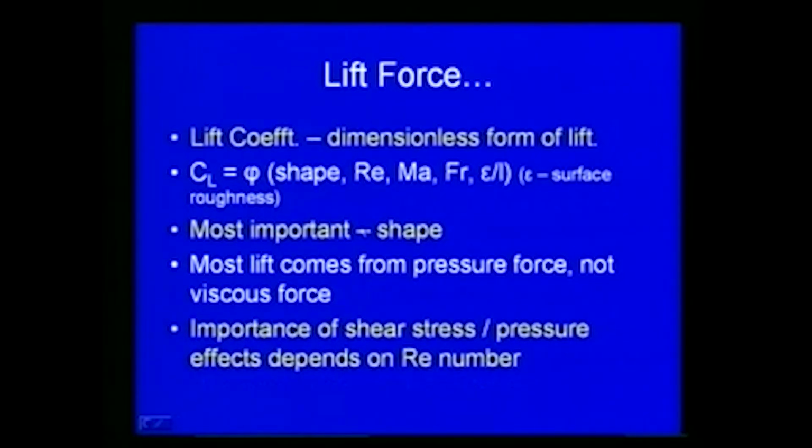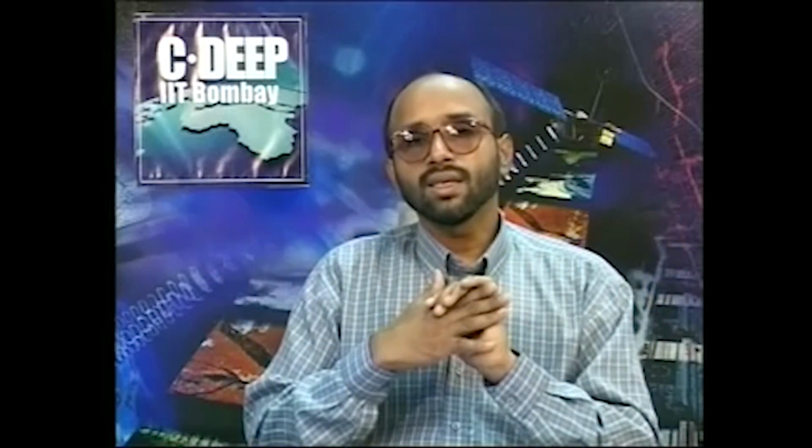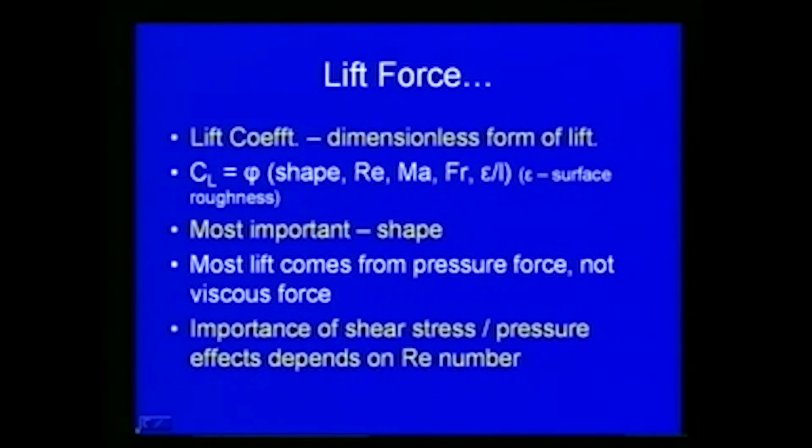We can see that this lift coefficient is a dimensionless form of lift. As we discussed in the case of drag, the lift coefficient or lift force also depends upon the shape of the body, and various fluid flow parameters like Reynolds number, Mach number, Froude number, and also the surface roughness of the body which we consider. So the lift coefficient here is a function of the shape of the body, the Reynolds number of the flow, the Mach number of the flow, the Froude number, and the surface roughness ratio epsilon by L, where epsilon is the surface roughness.